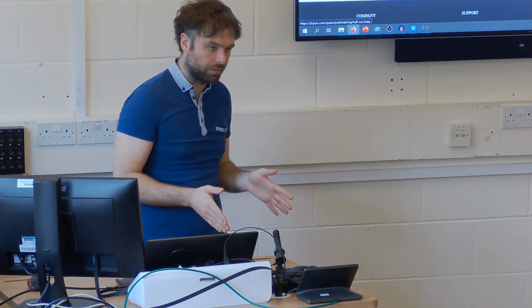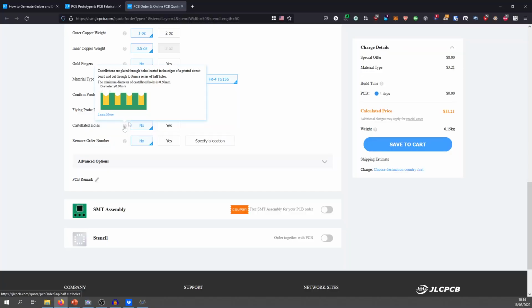So you imagine on the daughter board, you've got a bunch of through hole pads, and then you cut right down the middle of them. So the inner of that via there is exposed. Yes. So the solder would go onto a pad on the motherboard that comes out a bit like that. So this would essentially be like a chip that sits on top of the motherboard, and then the pads on the motherboard would come out underneath this part, and you'd put a big blob of solder, and it would connect all that together.